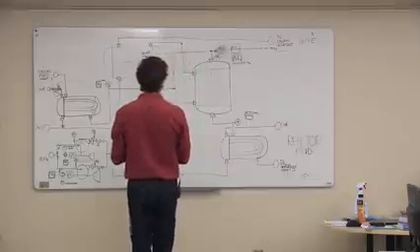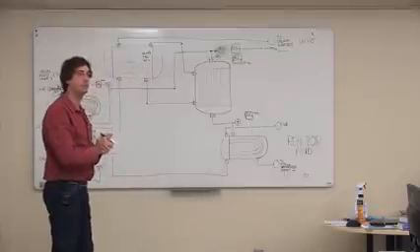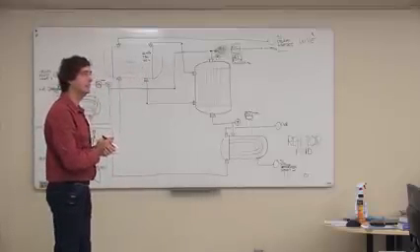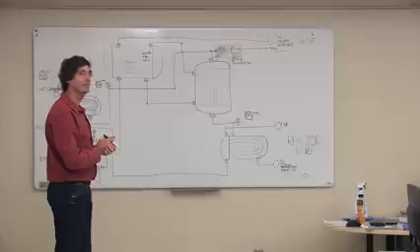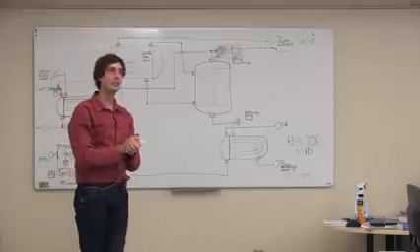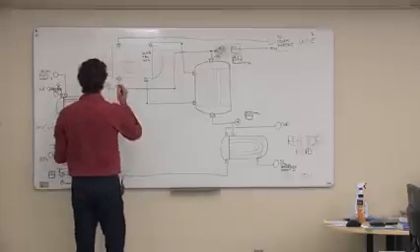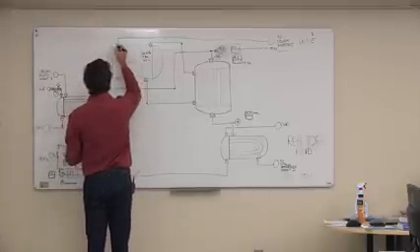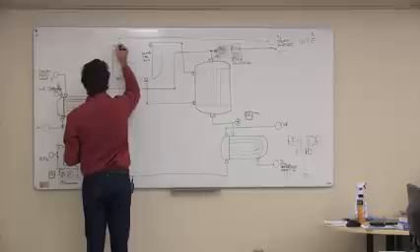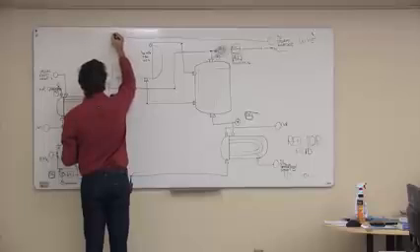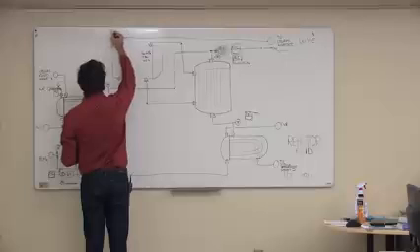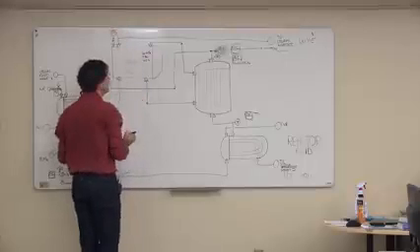What do we need to do that? We need to measure the pressure. Okay, so let's get that on there. Let's put it here. Put a pressure transmitter in. Like that. So we got a transmitter.